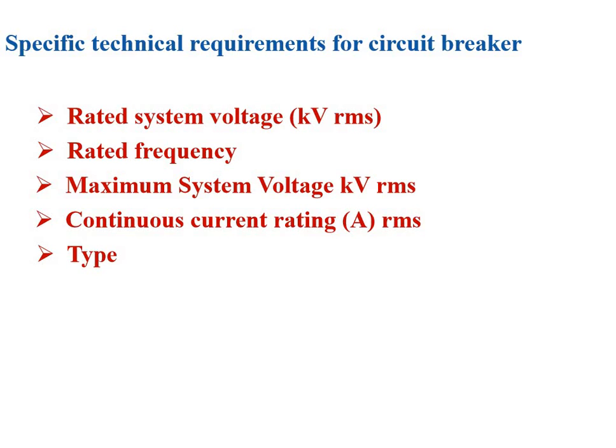So as per your requirement, where you are going to install that circuit breaker, and what the voltage of your system is, because there are LT circuit breakers, HT circuit breakers, and UHV circuit breakers also. Depending on the system voltage you have to decide, depending on the location you have to decide, and depending on the insulation medium used in the circuit breaker.